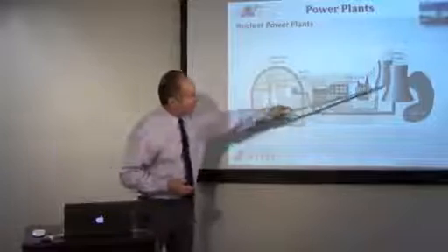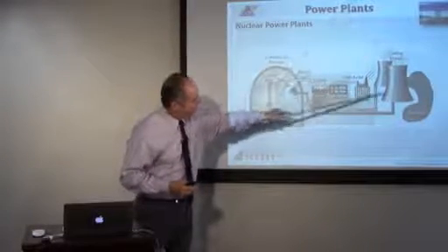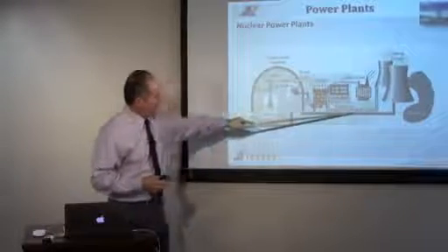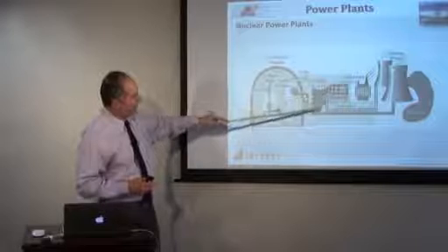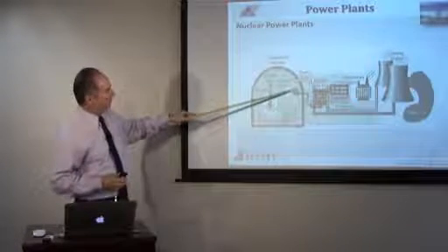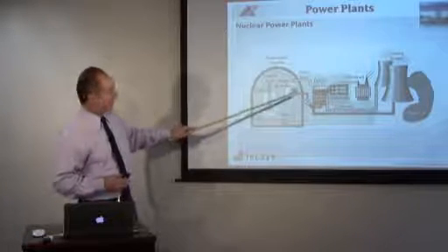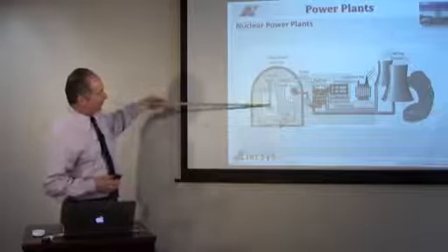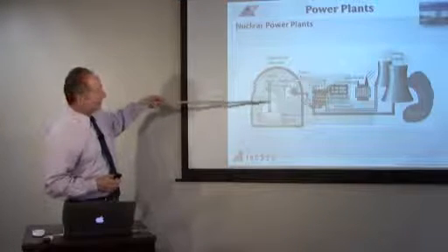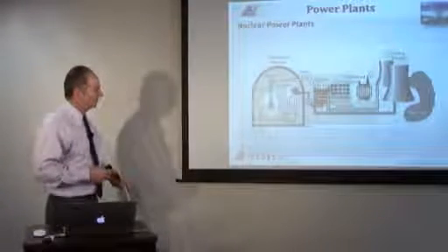So we're using the reactor to produce heat, to heat exchange into a secondary water system, which is then going through the turbine blades, and back to being condensed. This time it's condensed through cooling towers where air goes under and up. We're bringing heated water back cooler so we can condense the water flowing through the reactor back into the containment structure where it's superheated again. Now we have control rods here, which if dropped down would turn off the reactor, and lifted up would increase the heat reaction in the reactor.